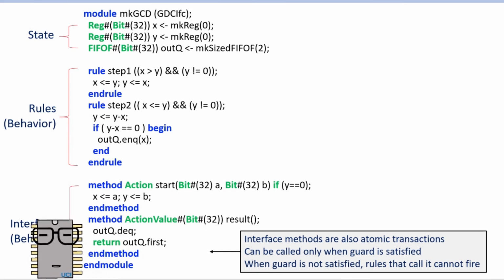This is the same for Verilog, for VHDL, for Chisel, for everyone. The effects of a statement are only visible to anyone else after the end of that particular clock cycle. After that, the effects of any of these statements become visible to the outside world.